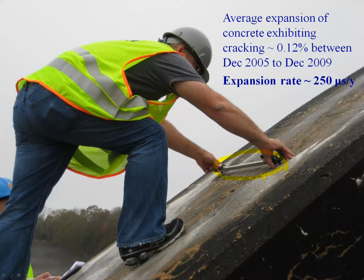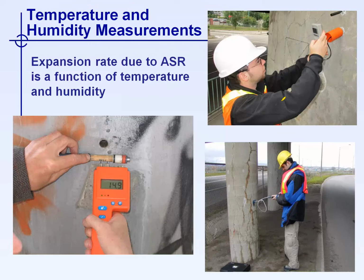And we've been measuring expansion in different portions of this structure, and we have found over a 4-year period that the expansion was about 0.12%, which corresponds to about 250 microstrain per year, which is considered as a high rate of residual expansion or progressive expansion. So the monitoring of expansion can provide useful information to evaluate the progress and the future potential for expansion.